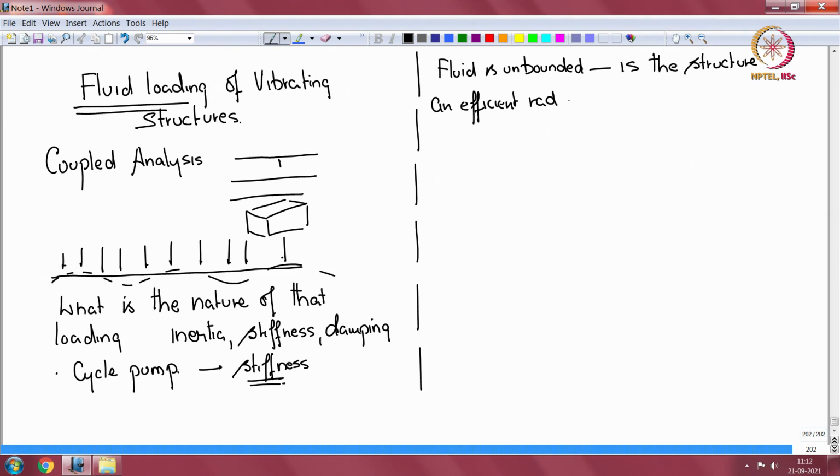There the fluid loading issue is whether it is inertial, in which case the fluid locally exchanges energy with the structure and no far field sound is generated, or the fluid loading could be in the form of damping, which means sound is transported away from the structure. So essentially that's the question we ask.